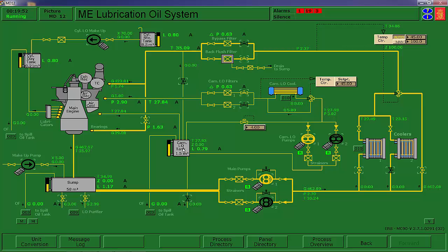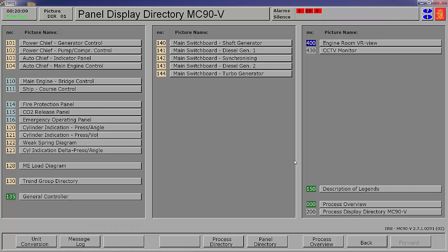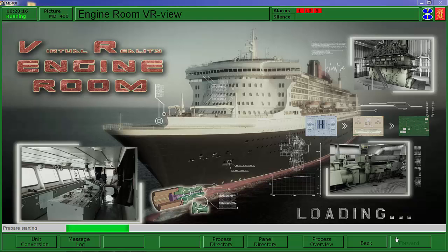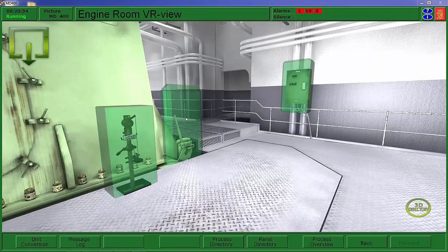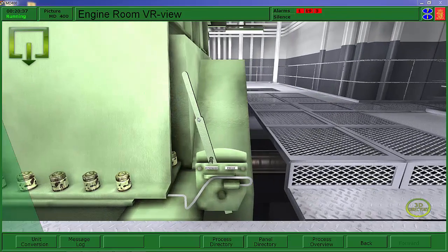Nothing to do with the camshaft as far as the bearings being different. It's because the fuel pumps, the high pressure fuel injection pumps on these designs, leak a little bit of fuel into the oil. All right, once this is done, we're going to immediately go turning gear in and start the engine revolving. To do that, we'll come down, engage the turning gear.